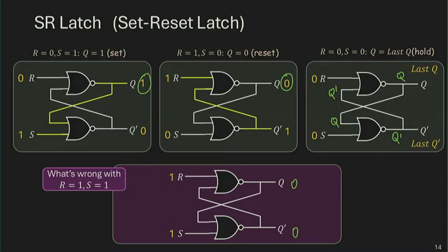We call this Q prime, so they better be complement to each other. In all of those previous cases, they're complement as two concrete binary values, and over there they're complement to each other based on this variable Q, essentially the state from some previous execution. And over here, we get 0 on both Q and Q prime. If Q and Q prime actually carry some meaning, that is an invalid condition.